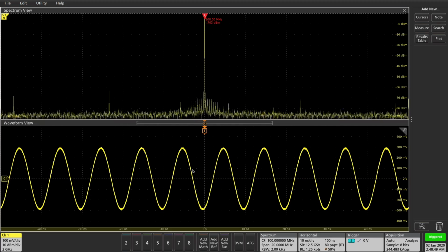You can see it's very sinusoidal. Now even though this tone is supposed to be ideal, you can already see some tones and various other harmonics around. The reason is because of the internal operation of the DAC, and there are some mixing terms and some clock divisions and some switching noise and so on, which will always show up. But these are again very small. The output amplitude of this sinusoid is 0 dBm roughly, and the difference between these tones is over 70 dB. So it's pretty impressive to see them at all.